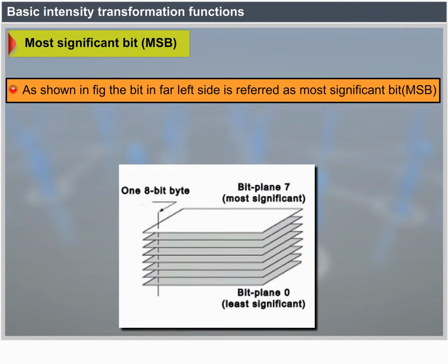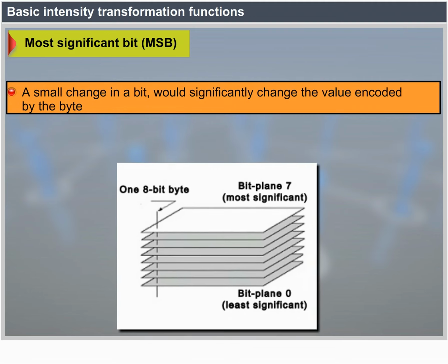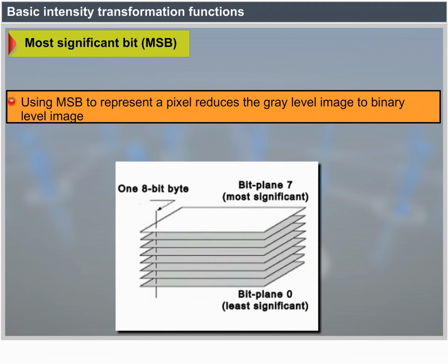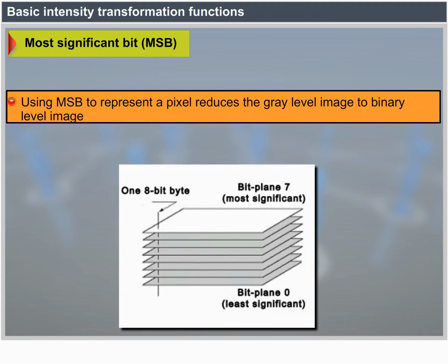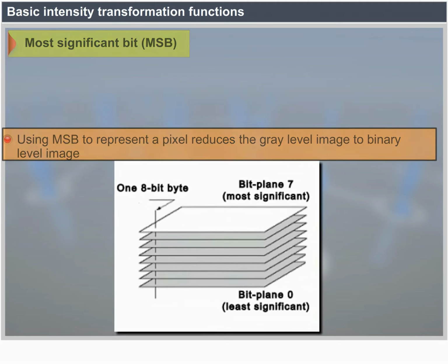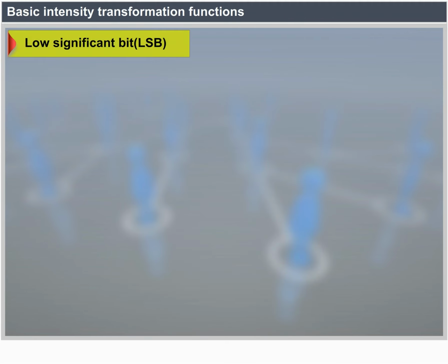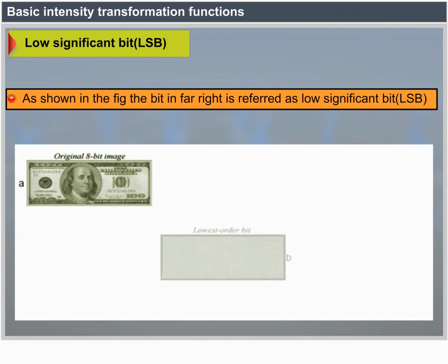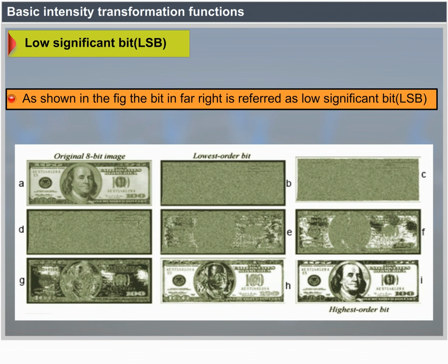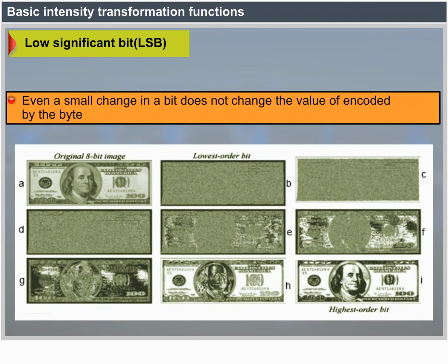Some properties of the 2D discrete Fourier transform. Relationships between spatial and frequency domains. If delta t and delta z are the separations between samples, the separations between the corresponding discrete frequency domain variables are delta u equals 1 over M delta t and delta v equals 1 over N delta z.